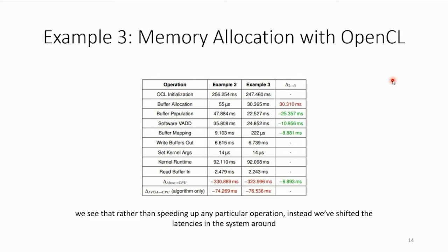It will check if the user application does not allocate memory at 4K alignment, then it will trap and copy to another memory to make sure that buffer is 4K aligned, and then transfer the data to the FPGA using the FPGA DMA.